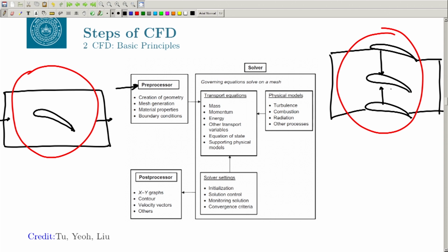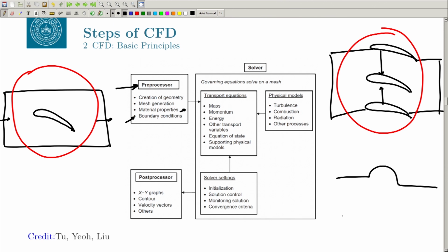But this is a step which can differ, you can define it in your solver also. And you can also define a boundary condition here, or you can define it in your solver. But whatever you define, you need to take care of that during the gridding stage. For example, if you are doing a periodic boundary condition, what is on top is on the bottom also.